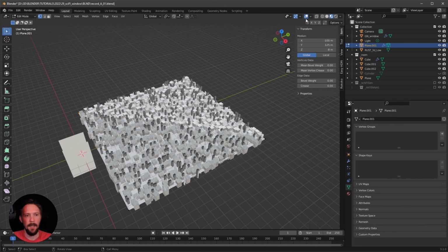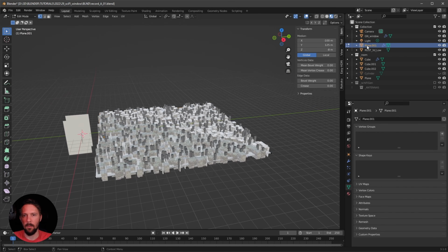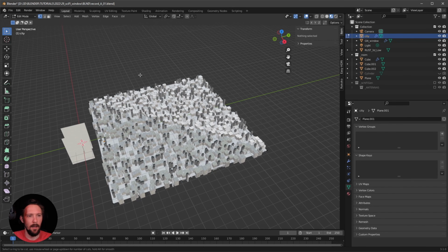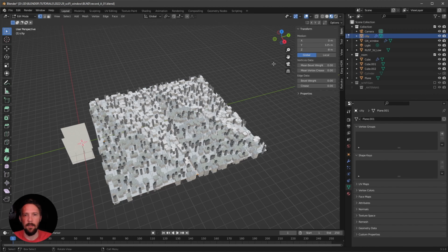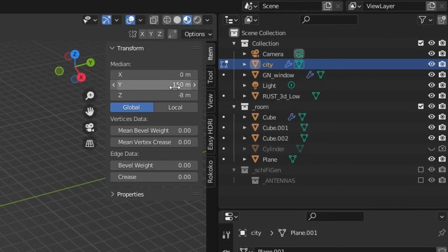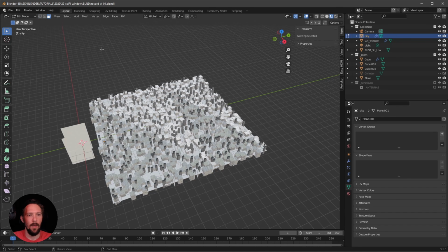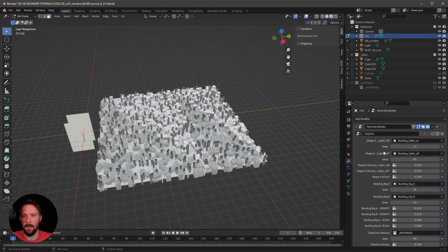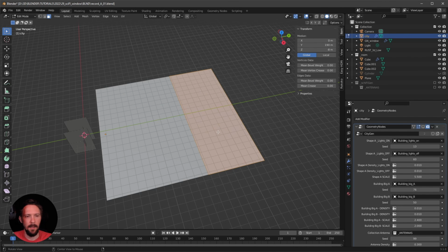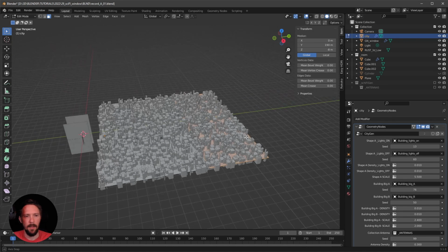And now we can go ahead and make some more stuff here with the city. Now I'm here in the edit mode and I want to make a loop cut. So press Ctrl and R, and then you will get here a line in the center. Press Escape, and now we want to bring this into the Y, which will be 150. And now when we are going into the face mode by pressing 3 or this button here, maybe when we turn this off, or into the solid mode, we can select this part.